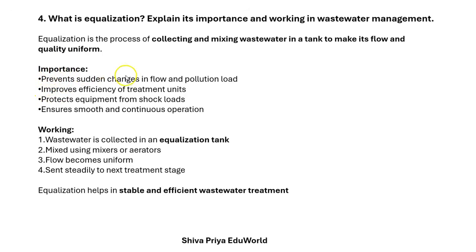It prevents sudden changes in flow and pollution load, and it improves the efficiency of treatment units as well. It protects the equipment from shock loads as well. It ensures smooth and continuous operation. This is why we prefer equalization.